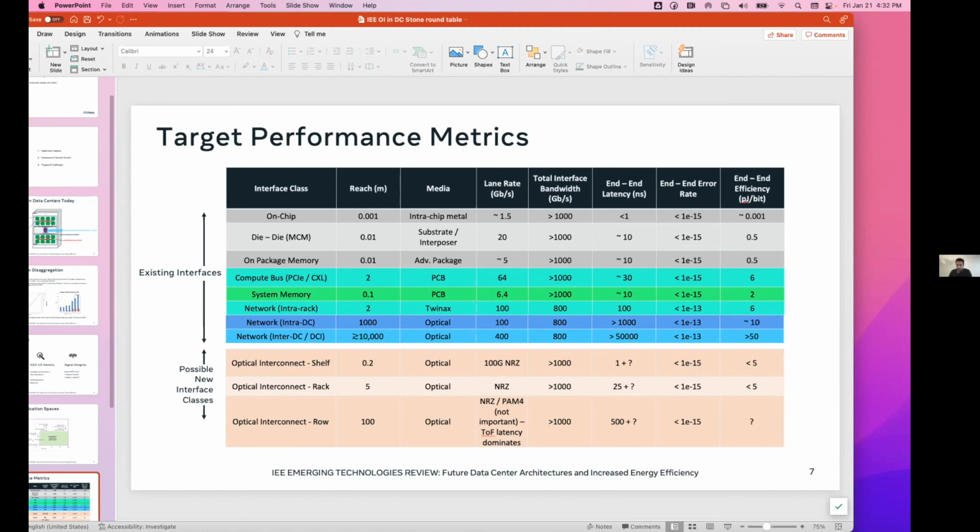Yeah. You mentioned the 128 SerDes, so does that correspond to a die edge of about 20 millimeters or something? I don't have that right offhand. You can look at the cartoonish die photo; we've published a white paper on the MI250X, but that goes on an OAM. So each end of the OAM has 4x16 SerDes, if you want to think of it that way. So 64 SerDes.